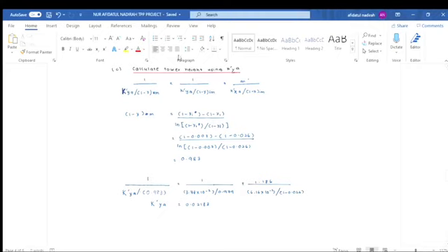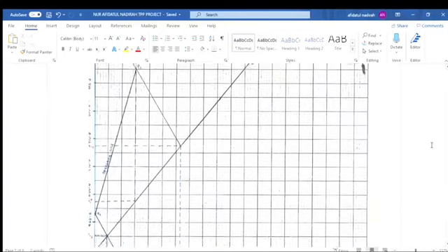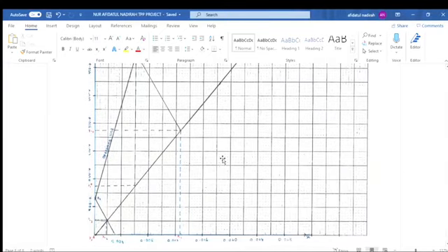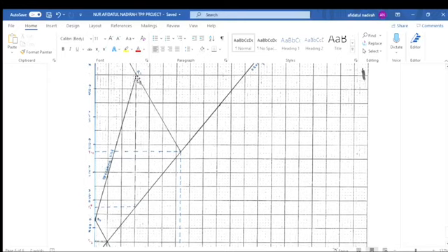So in order to get the value of y1 star, we can find it in the graph. We find y1 star and y2 star, where the y2 star we will use in the equation after this. We have to drag the points P1 and P2 to the equilibrium line. So this is P1, we drag it to the equilibrium line and move to the y-axis.